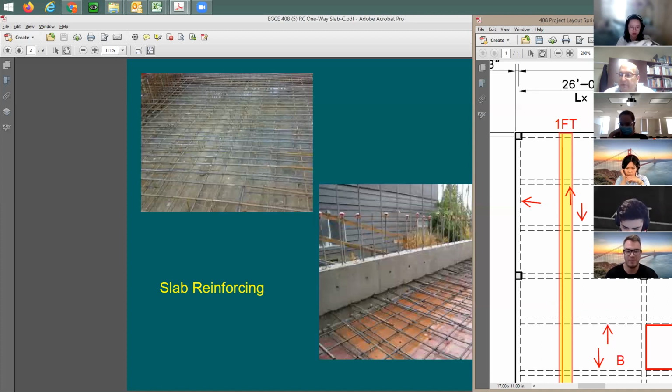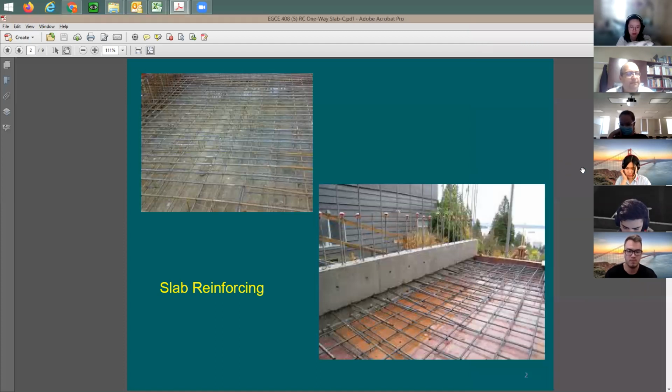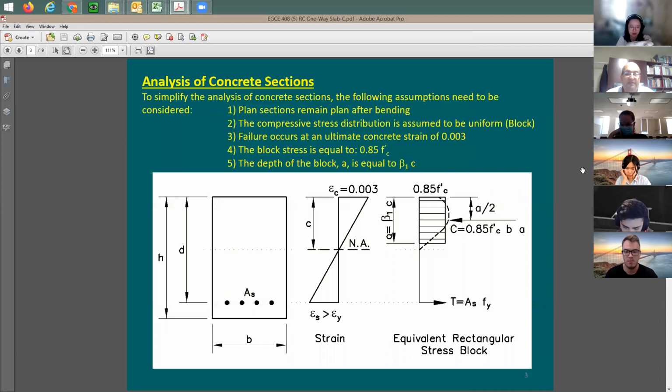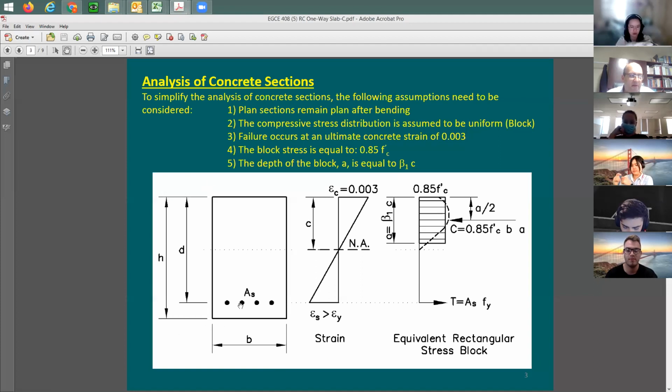Now this is going to be a pure rectangular section. There is no chance here for this concrete slab to be a T-section. This is the reason I can just use the same previous slide that we have discussed here and just use it in our analysis, in our design. Same width, but in slabs, this width is going to be only 12 inches. The depth is going to be equal to the slab thickness, subtracting the concrete cover and 1/2 of the reinforcing diameter.